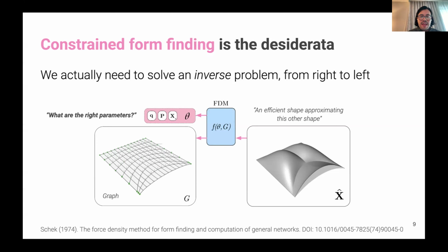So I was talking about gradient-based optimization. Here, the secret sauce is how we tune those parameters, those force densities, those applied loads, and those support positions iteratively on convergence. And the big picture here is that the parameter update is guided by this term highlighted in orange, which is the gradient of the loss function. And instead of doing that by hand, so that we have some analytical expression, which is what typically people do mathematically, here we delegate that task to the computer by using machine learning frameworks like JAX.